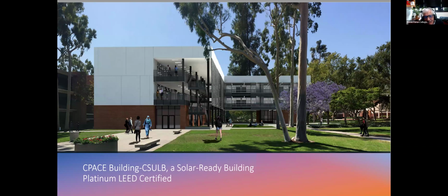It's a 3-story building. It's an L-shaped building, and it took advantage of the natural light, but at the same time, if you look at it, it has enough shading that it does not have direct light. So it has indirect light to reduce the use of electricity. At the same time, it also mitigated the solar radiation with this shading, to reduce the load on the HVAC system, the heating, ventilation, and air conditioning systems.